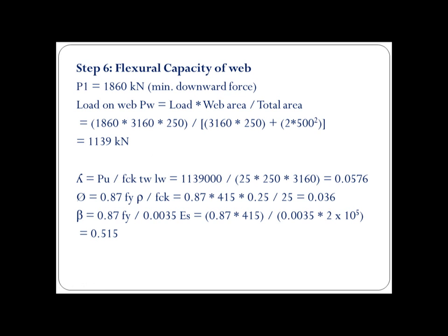So first is the axial load calculation, which needs PU. So we take the minimum axial load and maximum moment, so that we end up in the minimum capacity, or in the worst criteria, so that the wall is safe under all proportions, or under all categories.